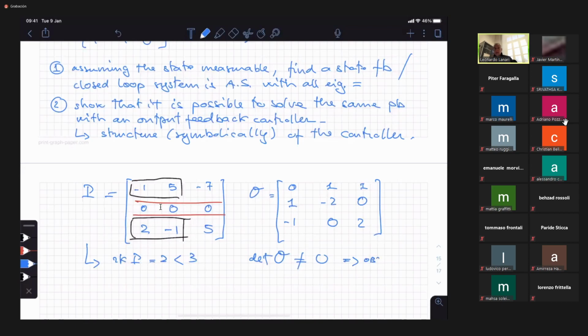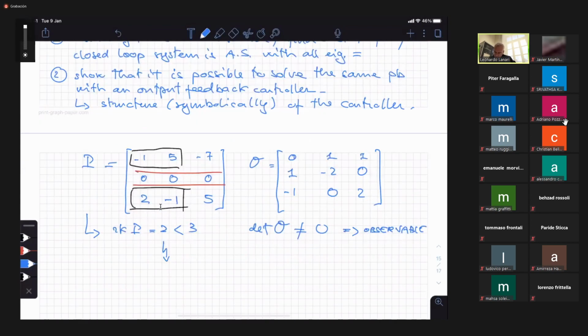We know that if necessary, we could build a dynamic observer with absolutely no problem. While answering the first question, we should either look at the eigenvalues and find out through the PBH test which one is uncontrollable.